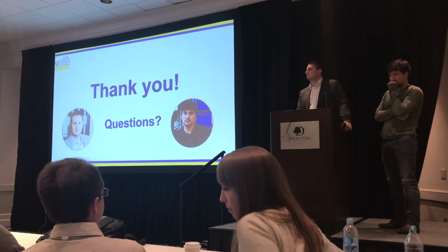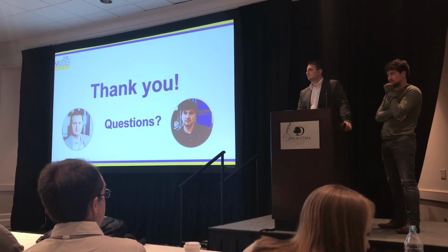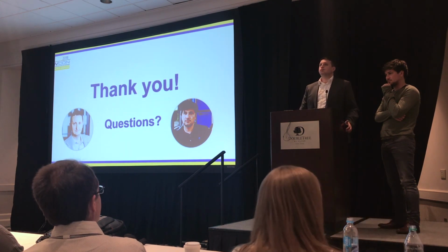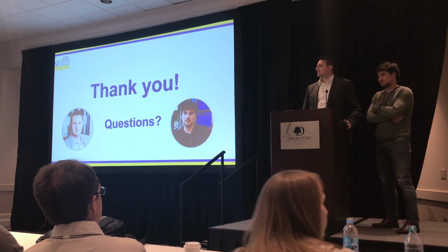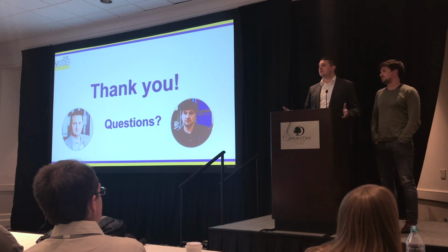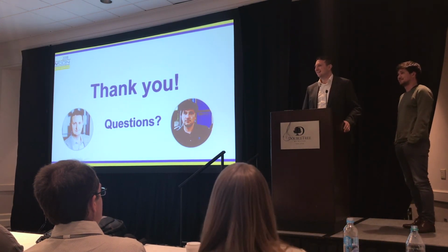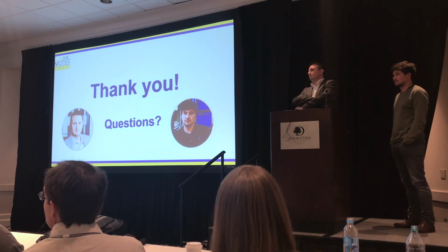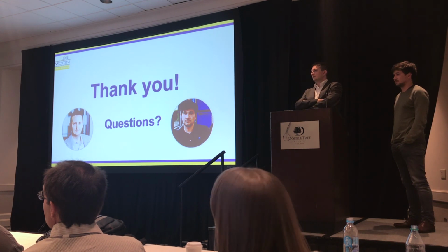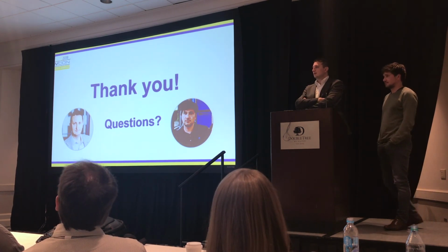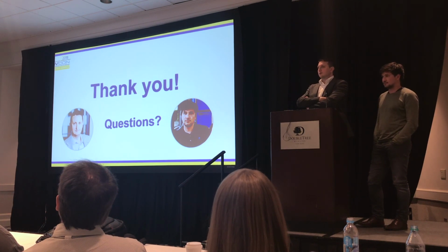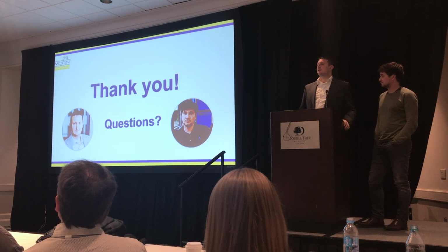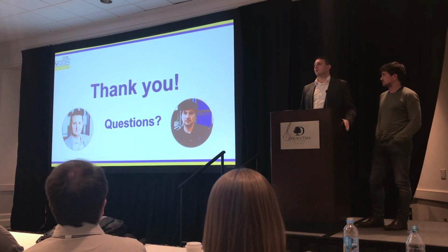So we've talked about code that isn't exercised, but what about a redundant property that doesn't need to be there, that can be cleaned out? I don't see properties as redundant myself, right? So if the property is proven on the design, you're welcome to keep it. I'm not really sure what you mean by redundant properties. So the one that makes the most sense is, what if you have an assumption that you didn't need? It's an assumption property as opposed to an assertion, but that's the one that makes the most sense of something you'd want to cull. I see. So if you have an assumption that is not needed to quantify, that would probably point you to overconstraining.